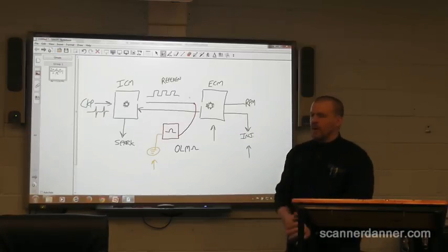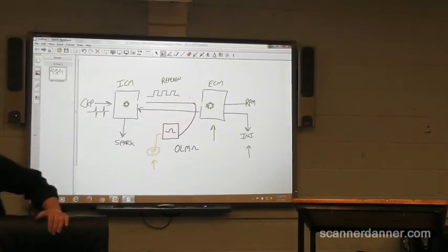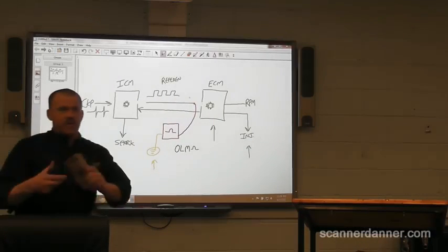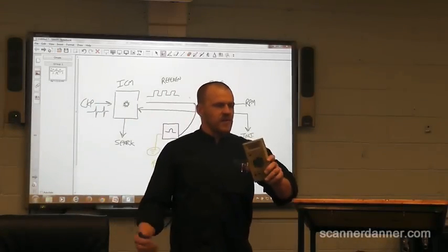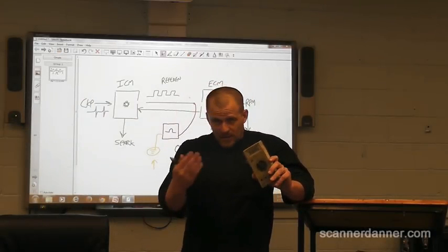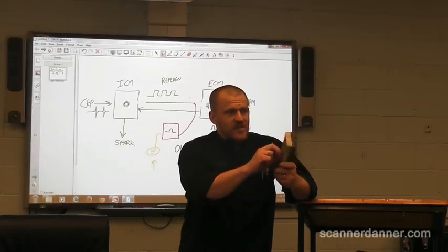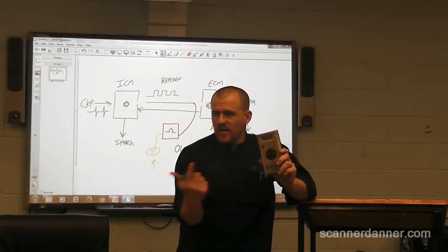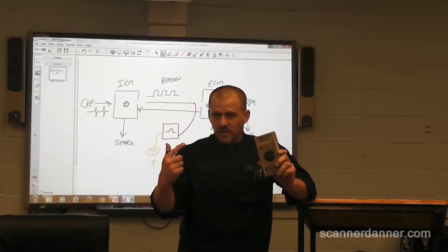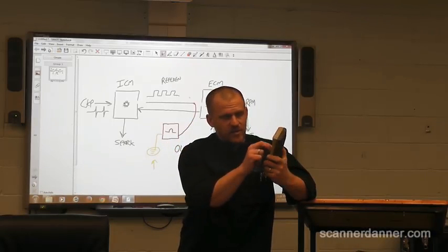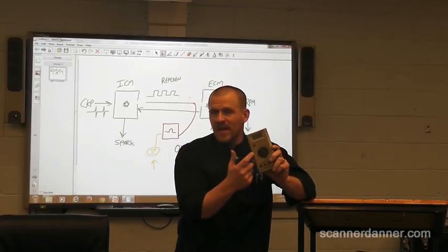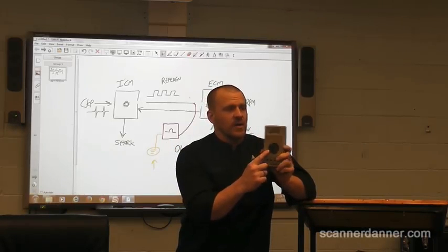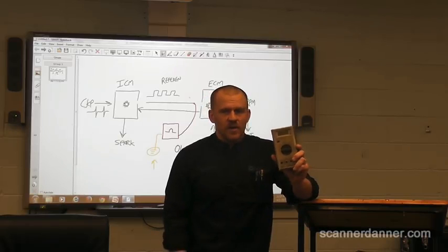But if you weren't on an auto ranging scale, think about this old school meter. You don't have to go buy a fancy meter. Some of the meters don't have auto ranging scales and you have to select them. So in this scenario, is it important that I understand these concepts and that I make sure I'm on the 20M scale, not the 200 scale? Because if I'm on the 200 scale, I might miss it.